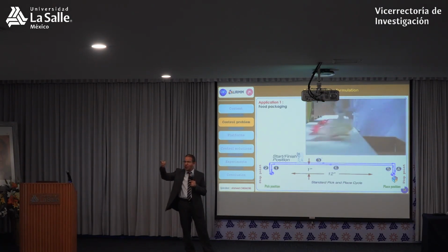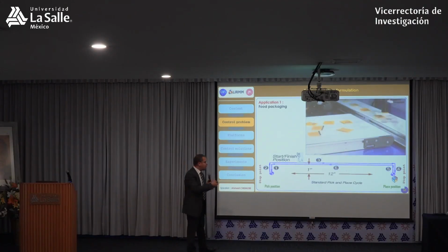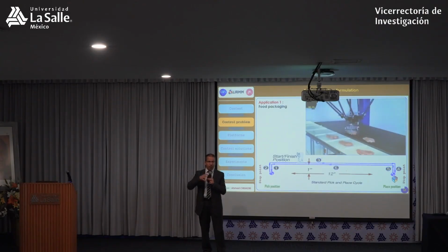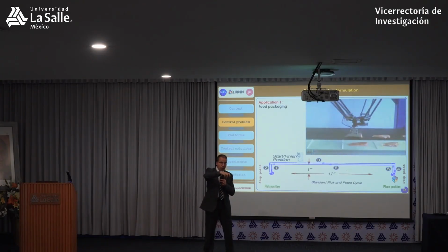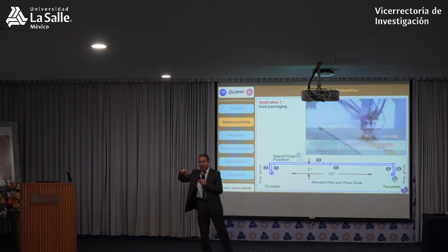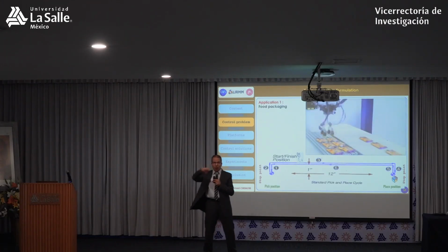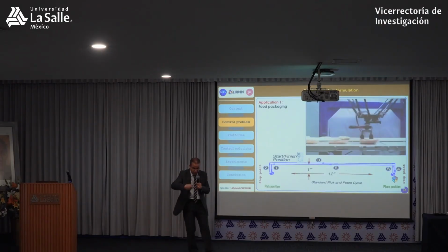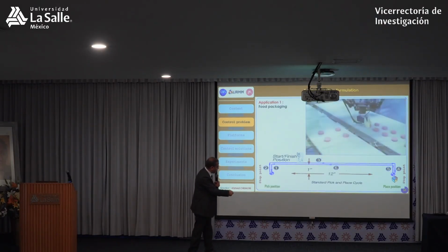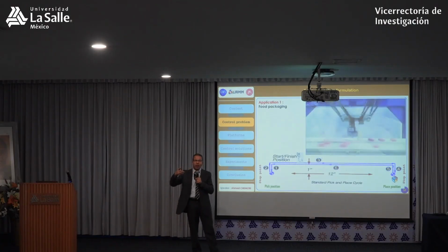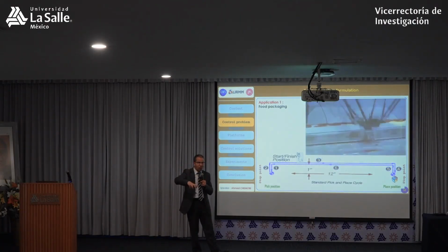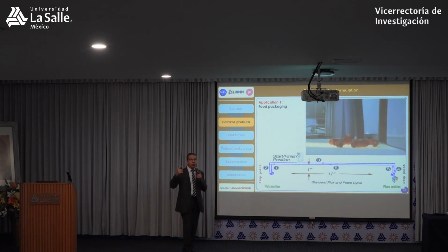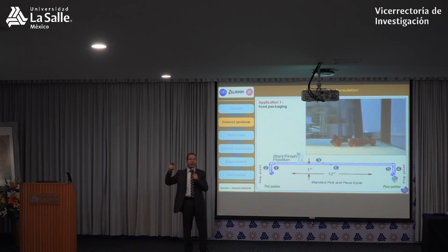However, if you increase the speed and the acceleration, pay attention, you will have two stop points. You have to stop to take the object, accelerate at maximum, and then stop to put the object, and then go back. And the problem is, when you stop here, you accelerated before, and you may generate mechanical vibrations. When you stop, you will have mechanical vibrations, and instead of reducing the cycle time, you may increase the cycle time.